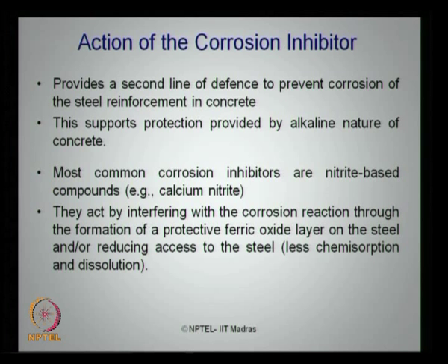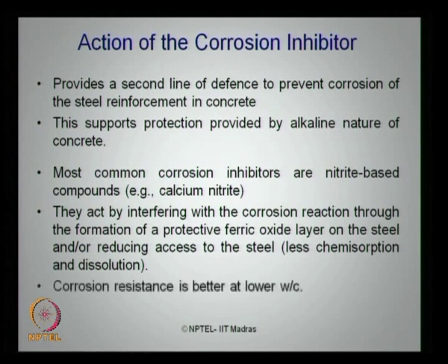They act by interfering with the corrosion reaction through the formation of a protective ferric oxide layer on steel, or by reducing access to steel, which means less chemisorption or dissolution. Corrosion resistance is better, of course, at lower water cement ratio.